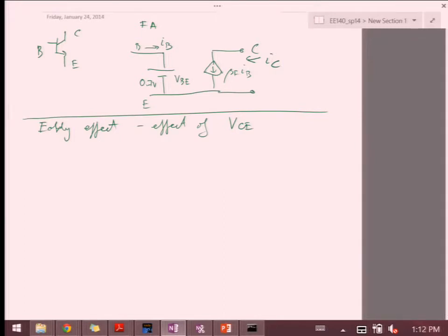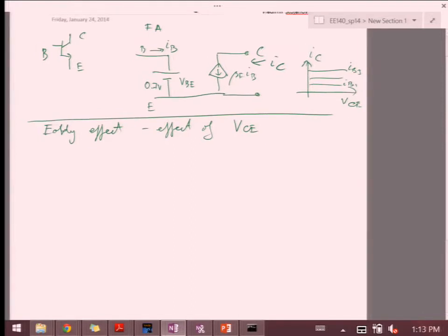Then my lines of IC versus VCE, the output, should just be straight lines, characterized by the value of the base current but nothing else, all the way till I get to this point of, let's say, 0.1 volt, where we said we enter saturation. We're going to cover saturation as a region as well. But in forward active, which is this zone here, we shouldn't get any dependence on the output voltage. Of course, that's the ideal transistor.